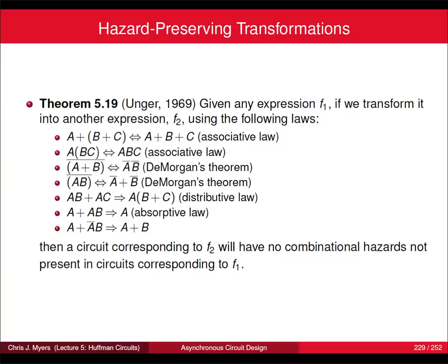But applying any of these laws might simplify, right? The absorptive law is simplifying it. Yeah, that's true. But it's not going to remove the redundancy that we've added for hazard freedom. This is like a smaller cube than that one, right? So that cube is okay because it's already there. And then that cube is just extra, it's going to be a subcube within that cube. So eliminating it is not going to cause you any problems in that case.